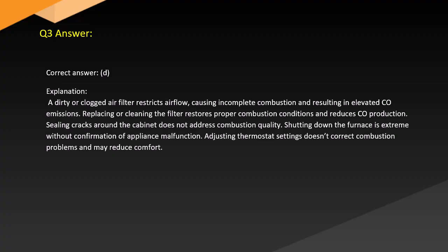Sealing cracks around the cabinet does not address combustion quality. Shutting down the furnace is extreme without confirmation of appliance malfunction. Adjusting thermostat settings doesn't correct combustion and may reduce comfort.